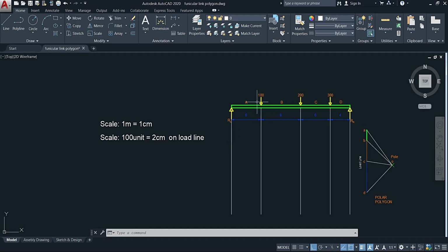Alright, so we have the forces here, and we have this force acting up, this force is acting up. So we have these two forces acting up, but we have three forces here acting down. So it means that in order for this beam structure to survive or not collapse, whatever is acting down, the minimum force acting up has to be the same thing or even more, if you want to think about it like that, in order for them to cancel out each other and everything to be safe.